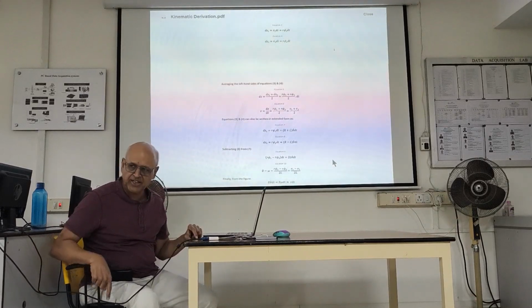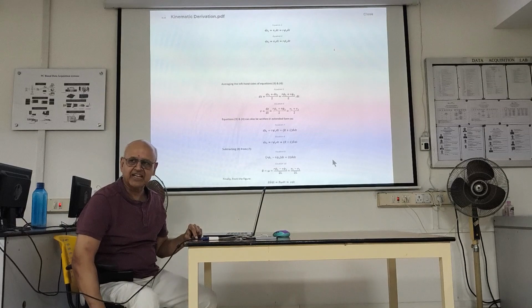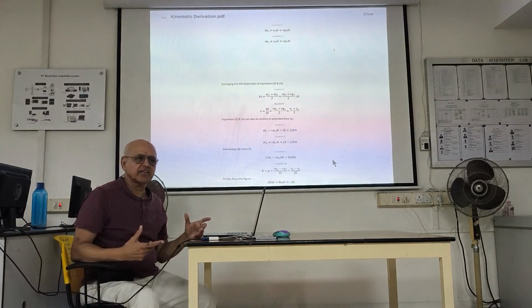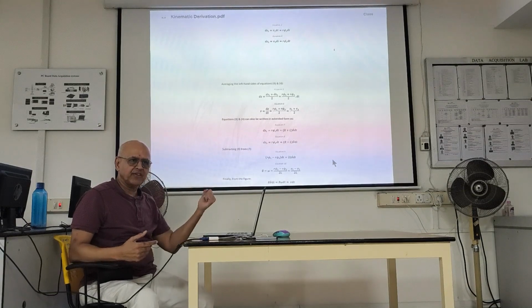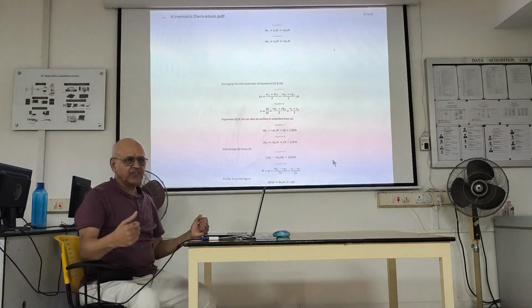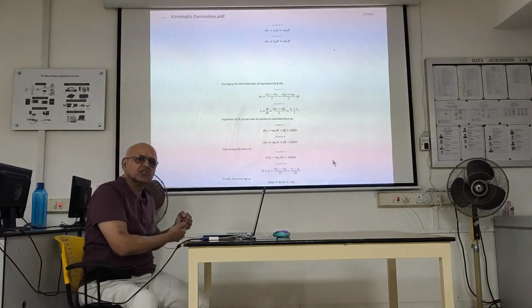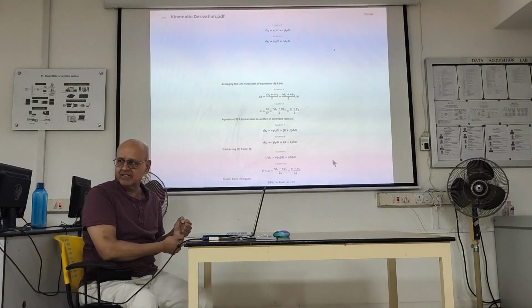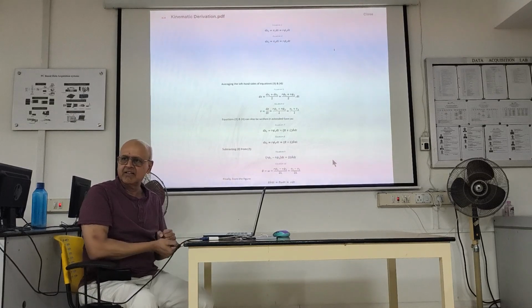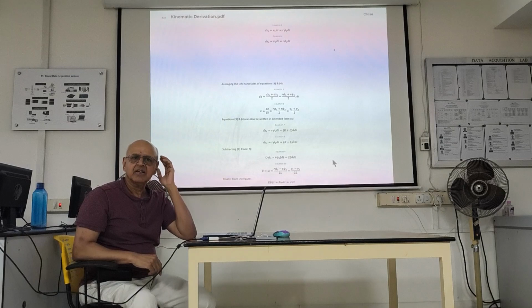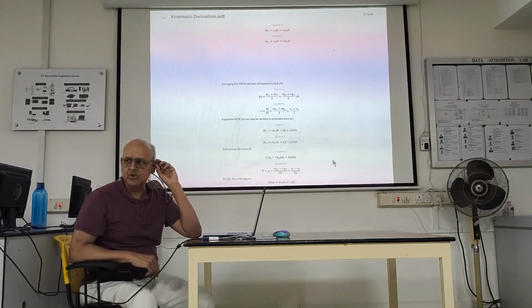The point is, we are rotating about the center, which is directly under the right wheel. So you can make a differentially steered robot do that too. If you stop the left wheel and you make the velocity of the right wheel negative, then it's going to rotate this way. But the stopped wheel will be the anchor. So that's how a differentially steered vehicle operates. I told you, till about 125 kilograms, they still use it.